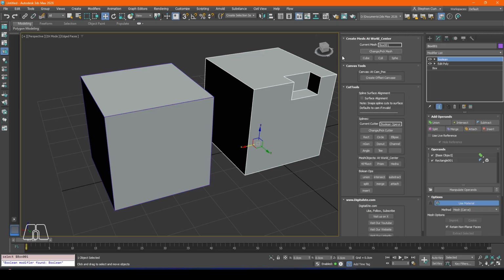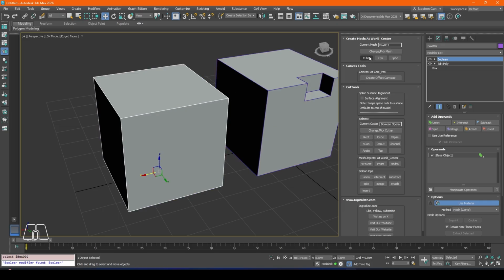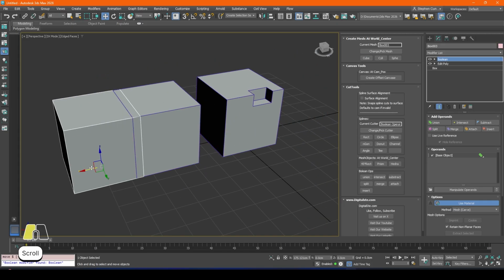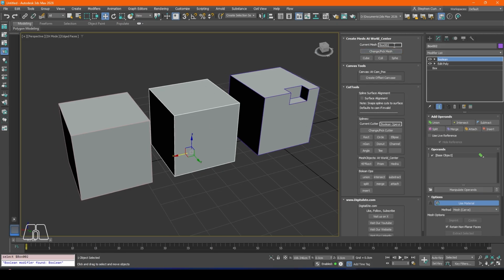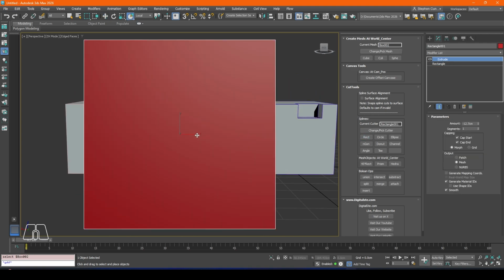we can change which option we want. Now by default, it'll select the newly created object. So in here, if we click here, you can see it'll default to object 3. Okay, so let's just put 3 there. And then you've got object 2. So now I've got to click that, and I've also got to click that one. So if we want object 2 and I click that, that is now going to become the mesh that is going to be Booleaned. Okay, so I'll just do another rect at position.